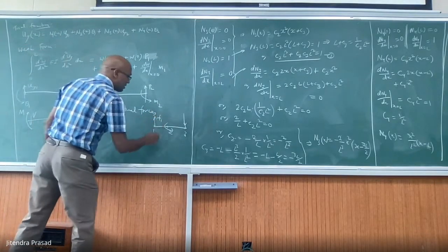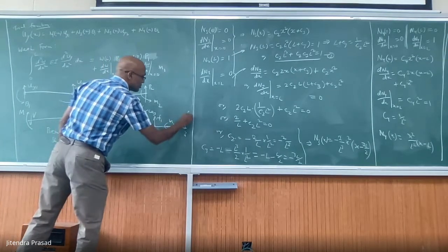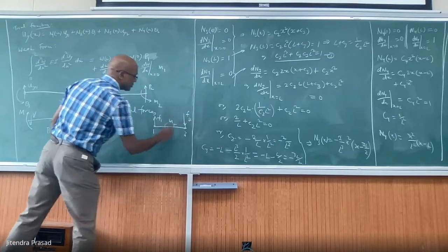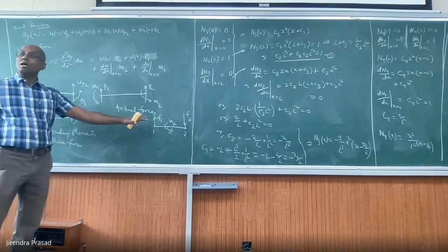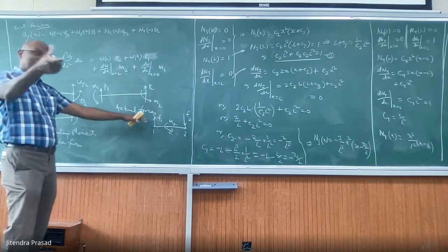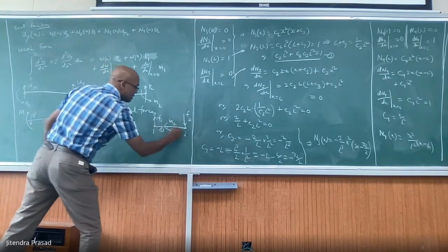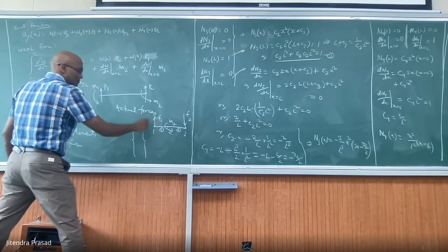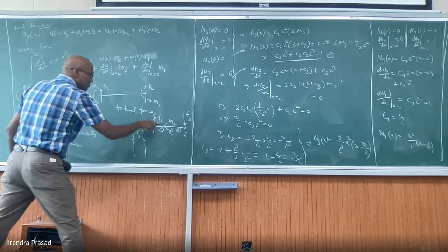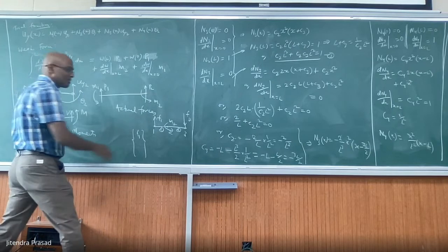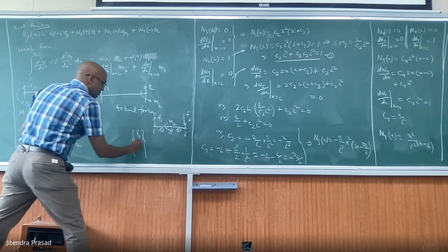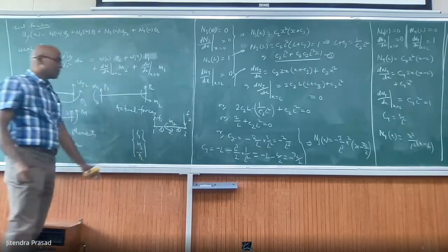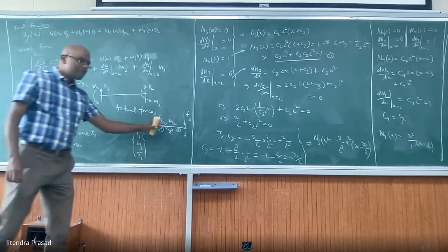Let's call it F1, M1, F2, F3. And they are the actual forces on the problem you are talking about. These are element number 1, this element number 2. The global force F1 is there. It will be positive or negative? Positive. Actual force you have to write, that's it. What about this M2? Positive because anti-clockwise. What about this? Yes. Your force vector is complete. They are forces only.